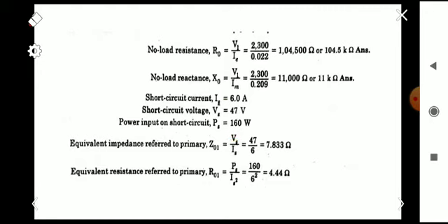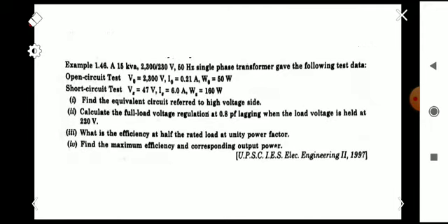First we have to determine on which side we are doing this test. Normally the short circuit tests are done with the low voltage side short circuited.